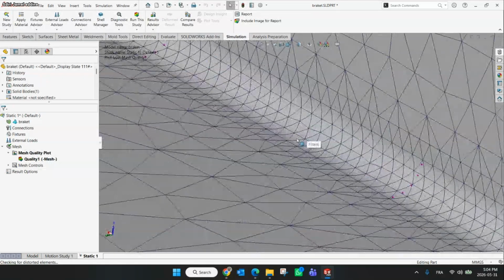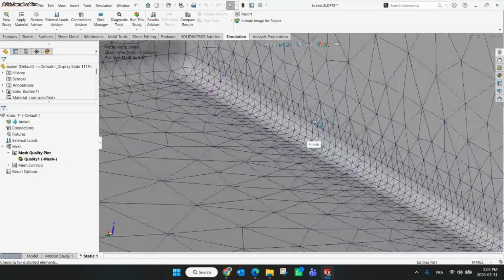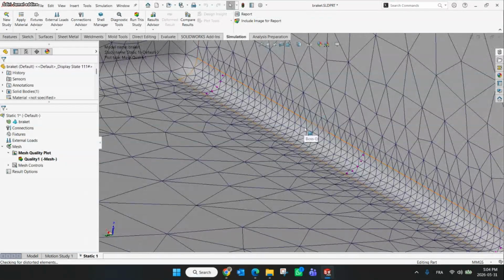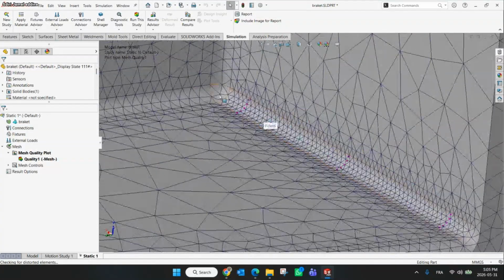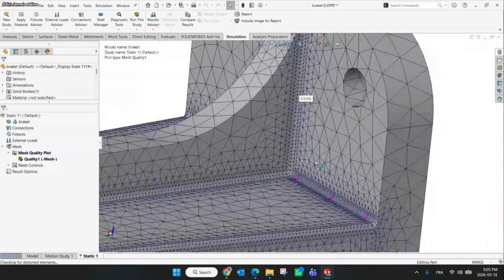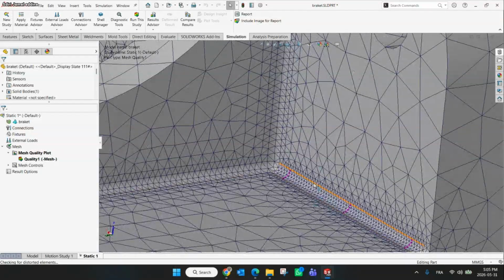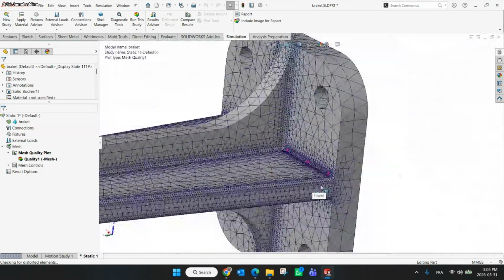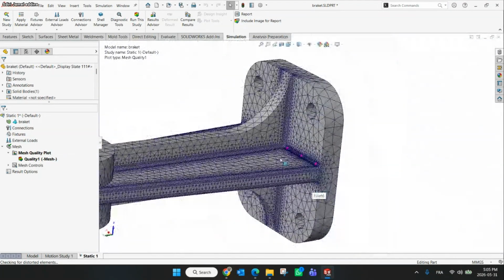As you can see here, we have 4 elements only on this region here, as we have 2 elements on the other region over here, because I refined the mesh for this specific area. These tricks are mostly used to have much more accurate results on a specific region where you want to predict the stress value or the displacement.